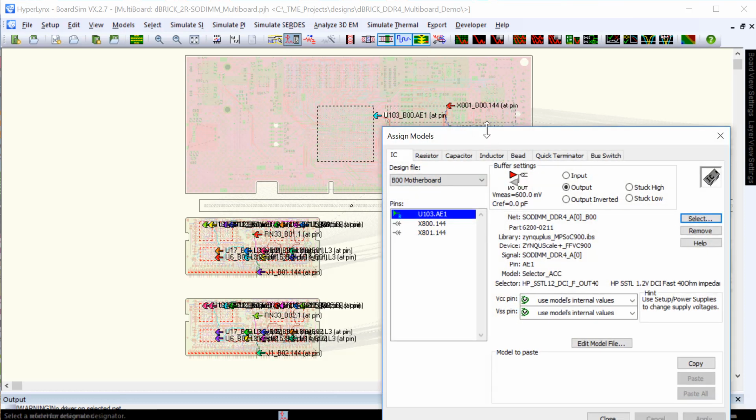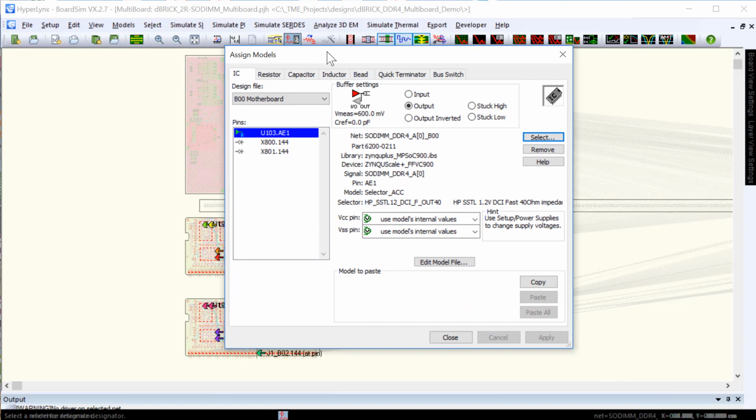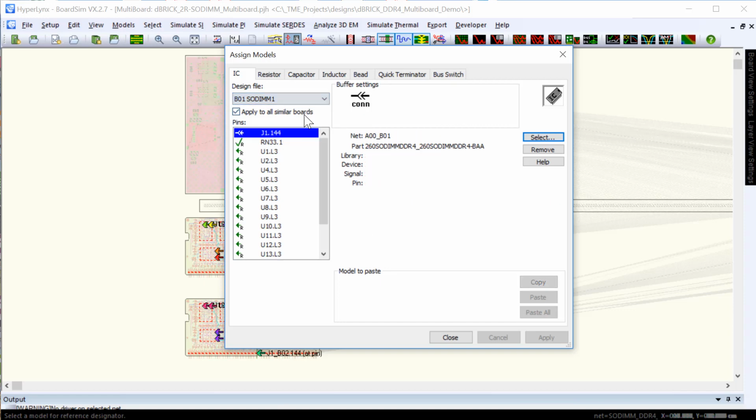If you look at the number of loads on one of the DIMMs, you can see there are 16 loads since the DRAMs are by 8 devices, so you need 8 DRAMs to form one rank of 64 bits. Since this DIMM has 2 ranks, you have additional 8 loads. If we look at the second DIMM, there are 16 more additional loads, so the address bus will have 32 loads on each net with this DIMM configuration.